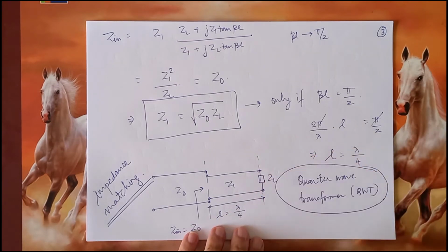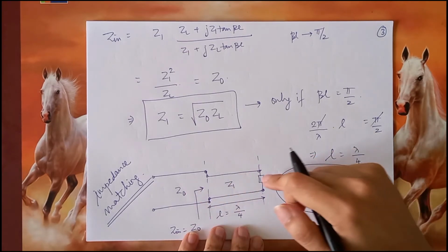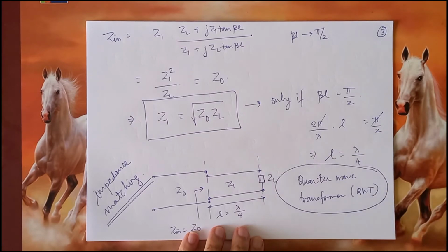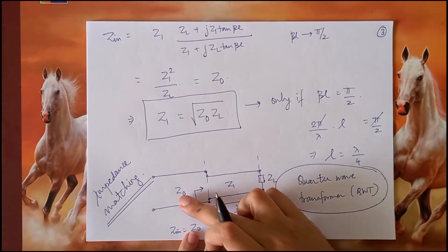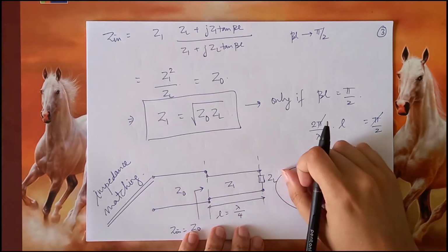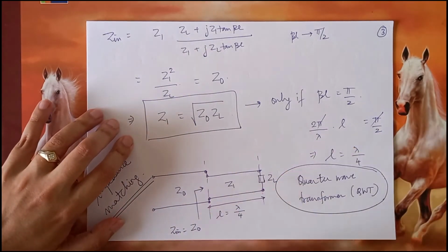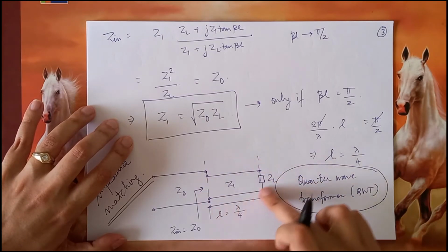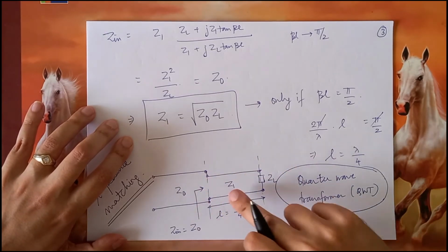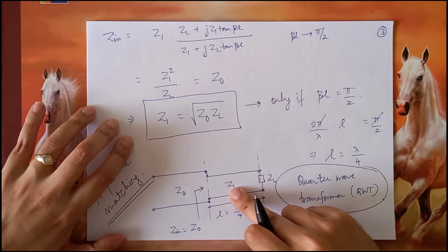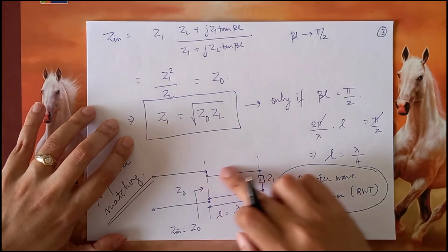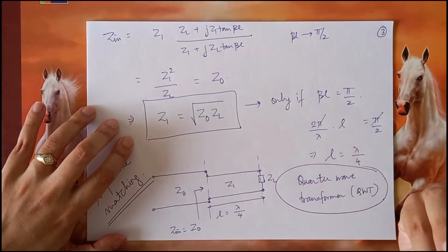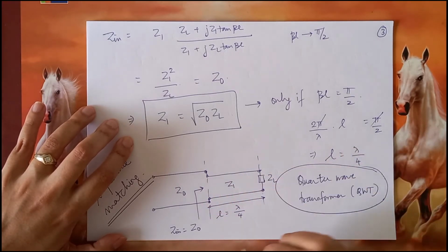Well, one technique we saw very easily, which we can apply for the case when both Z0 and ZL are real, is the QWT. Now we had mentioned that whatever is the impedance transformer or whatever is the black box, that must be lossless. And what did we use? We used a transmission line of characteristic impedance Z1. And is it lossless? Definitely it is lossless, because it is just a pair of conductors. So there is hardly any place where any energy or power may be dissipated.